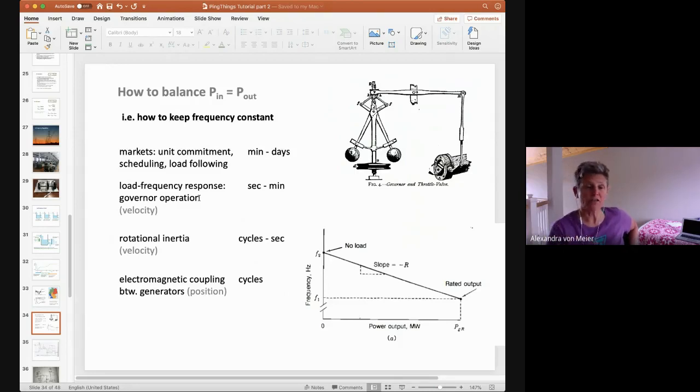And the technology to do that was developed by James Watt back in the day for the steam engine, with a really simple analog system where these two weights are going to fly apart as the rate of rotation speeds up. And it's going to pull on lever F, which pulls on lever B and on lever H. And then consequently, valve A gets opened or closed, which is just delightful.